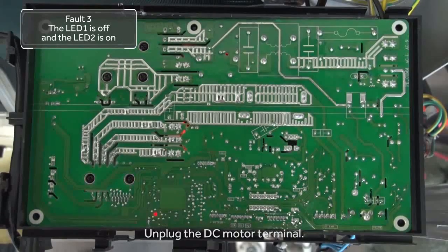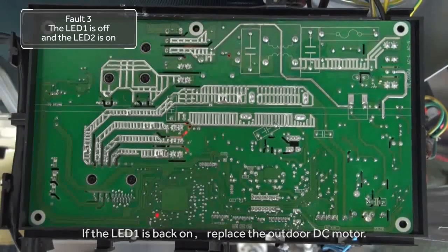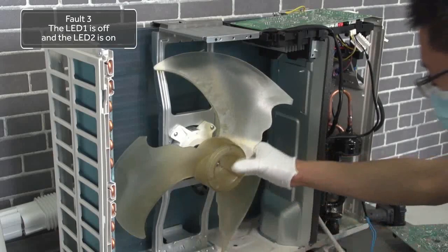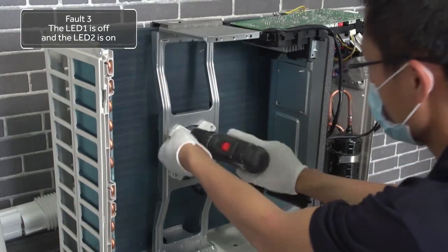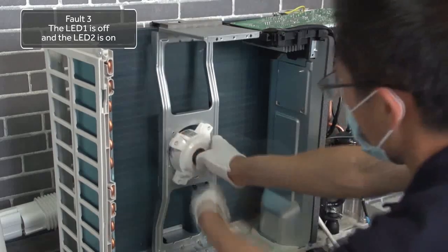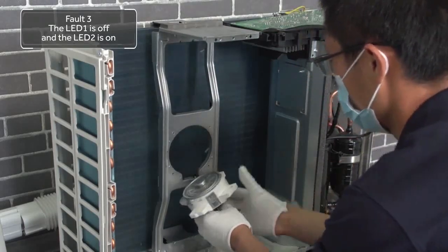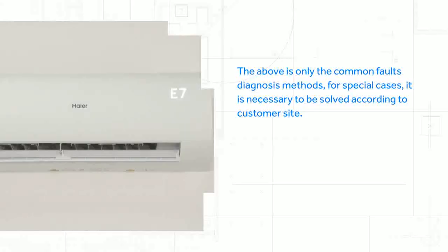Unplug the DC motor terminal. If the LED 1 is back on, replace the outdoor DC motor. The above is only the common faults diagnosis methods. For special cases, it is necessary to be solved according to customer site.